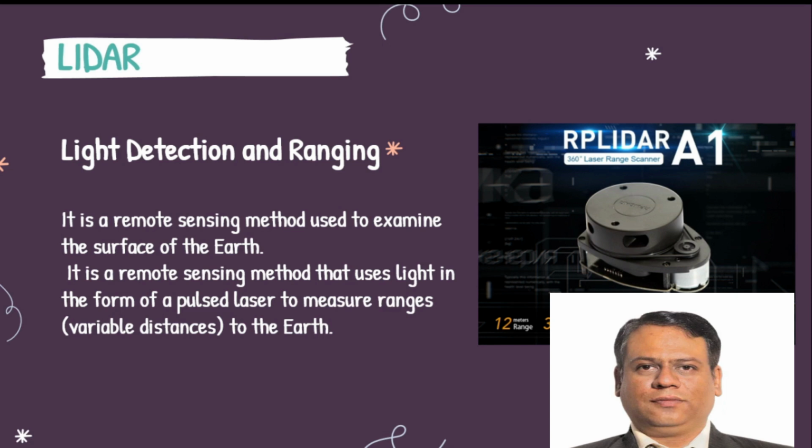Please be attentive in the session, because we are going to learn ROS and Lidar based applications in real time. It will be very great. So we are using a 2D Lidar, the RPLidar model A1, which is a 360 degree Lidar with a detection range of 12 meters. If you want a higher range specification, it is also available: the RPLidar A2. There are a lot of versions of Lidar, like 2D Lidar and 3D Lidar. Here we are going to use the RPLidar A1.